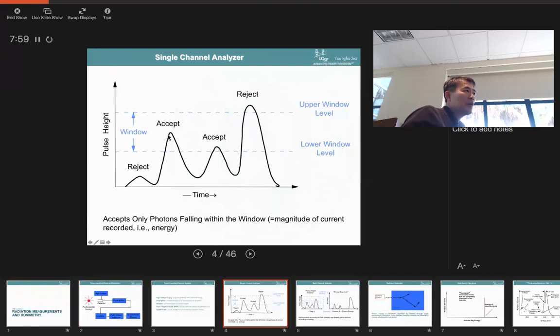The magnitude of a voltage signal from our radiation detector is related to the energy of an incident photon. Right? Remember we talked about how much of energy is generated from that interaction by calculating how many scintillation photons are really generated from scintillation process. We calculate all this just to know that incident photon energy is related to the final voltage signal, and the height of the voltage signal is directly corresponding to the energy of incident photon to the scintillator or direct conversion detector.